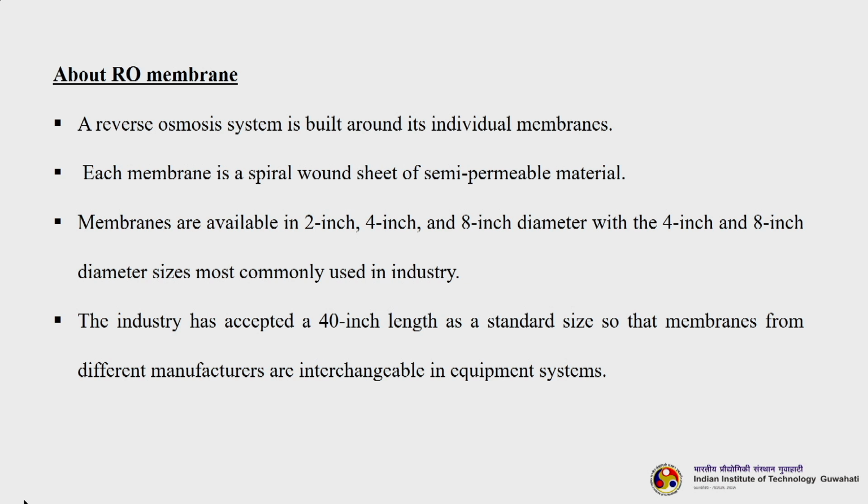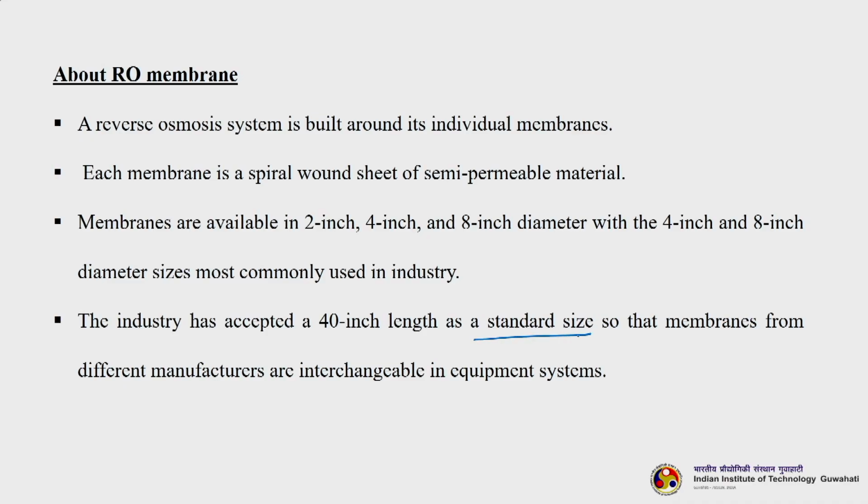Membranes are available in 2 inch, 4 inch and 8 inch diameter, and the 4 inch and 8 inch diameter sizes are most commonly used in industry. The industry has accepted a 40 inch length as the standard size, so that membranes from different manufacturers are interchangeable in equipment systems. All membrane manufacturing companies making especially RO membranes have agreed that 40 inch is the maximum length for their RO modules.